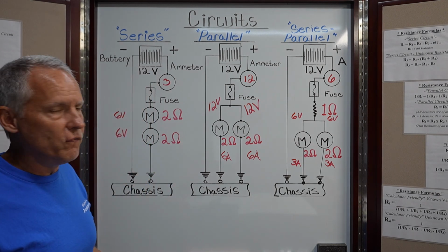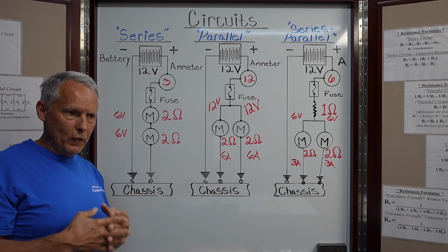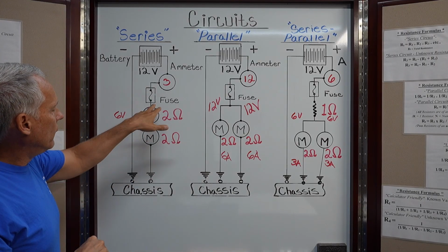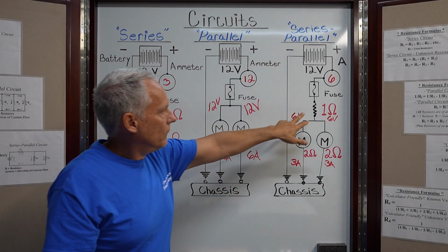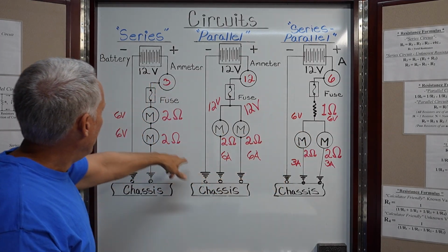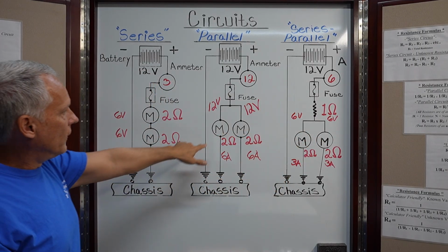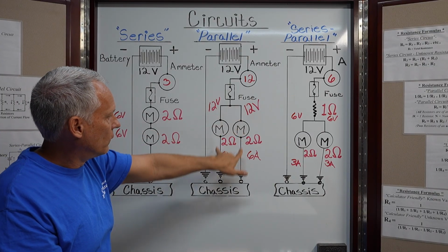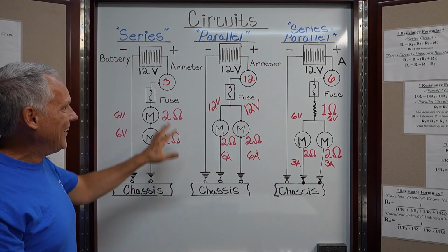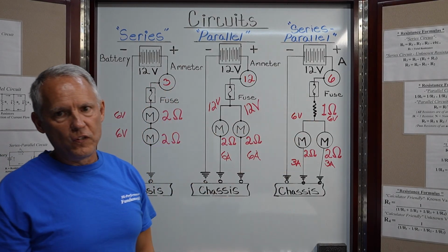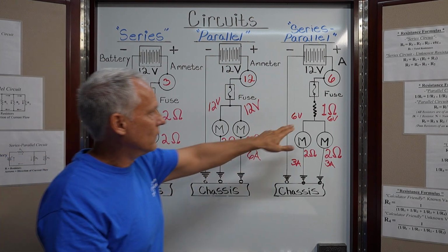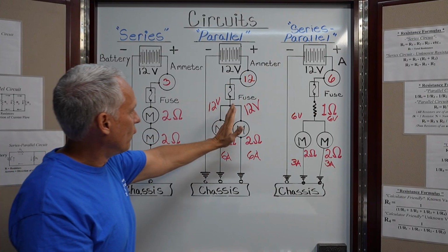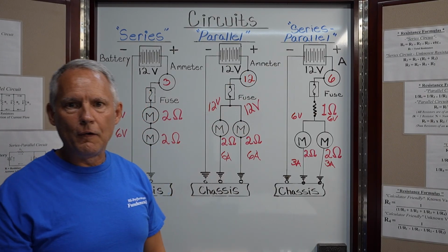But, like I said, through the creative use of three relays, General Motors does it like this. I can tell you for a fact that they eliminated this resistor altogether, right? And basically just ran them in series for low speed, and then they rerouted the wiring to change the direction of current flow through a parallel circuit. And this is now high speed, okay? They didn't need the additional resistor or the additional connections or anything else to make this circuit occur. So there's less expense, less complexity, right? So by doing this, they switch over to low speed, high speed, right? And that's how it's done.